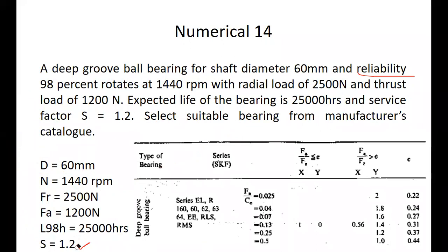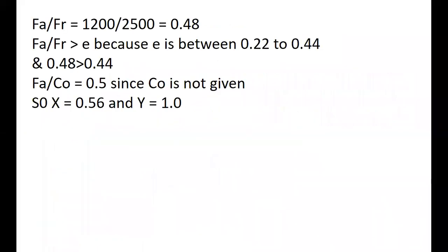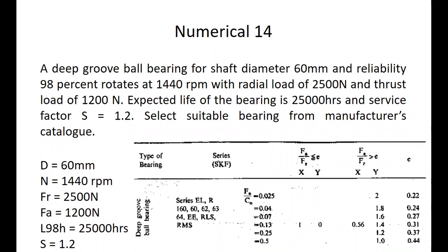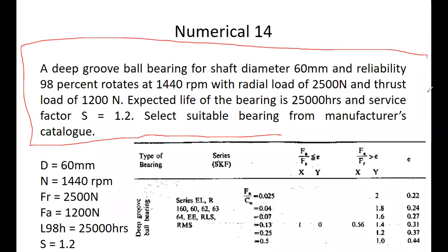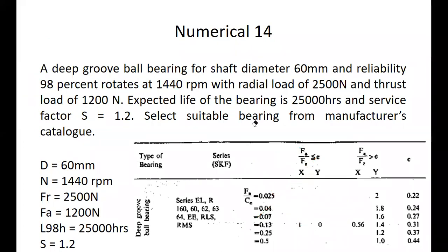Shock load factor, or load factor, or load application factor is 1.2, right? So let's start, guys. This time, first, when you see here, notice the numerical X and Y values are not given. This table is not given. This table is there in the Bhandari Design Data Book, right? So you have to use the table for X and Y factors for deep groove ball bearing. That table in the design data book you have to use.